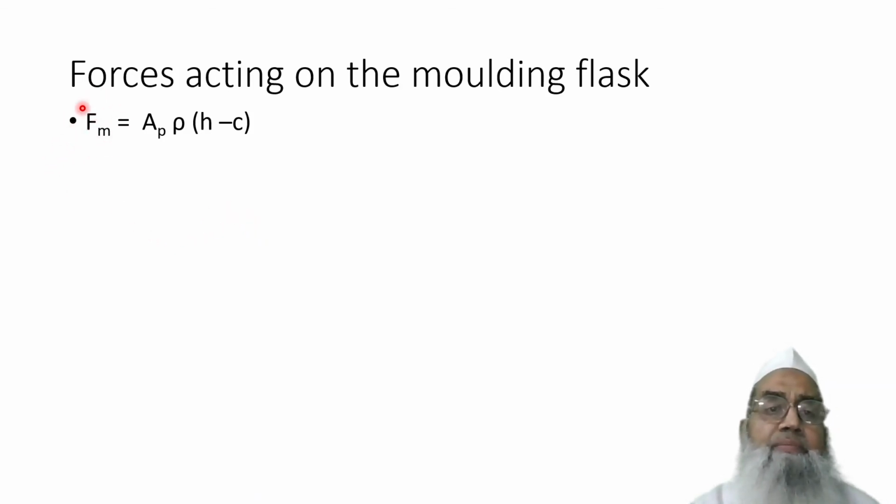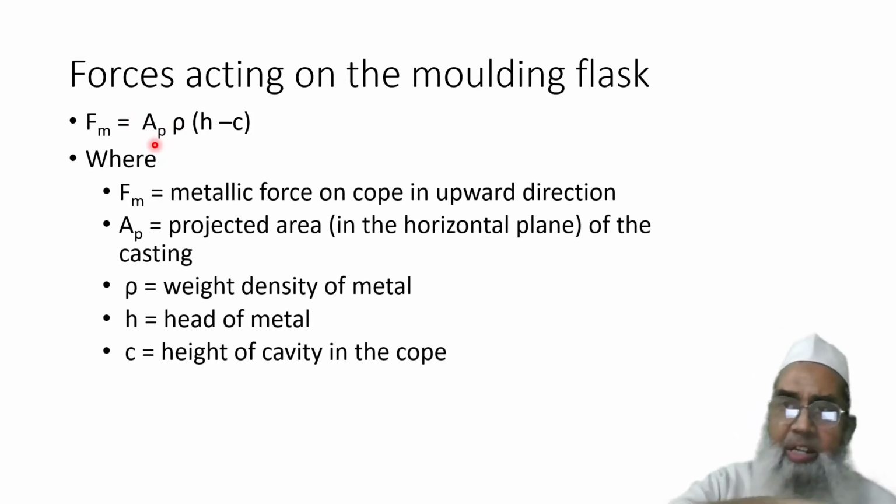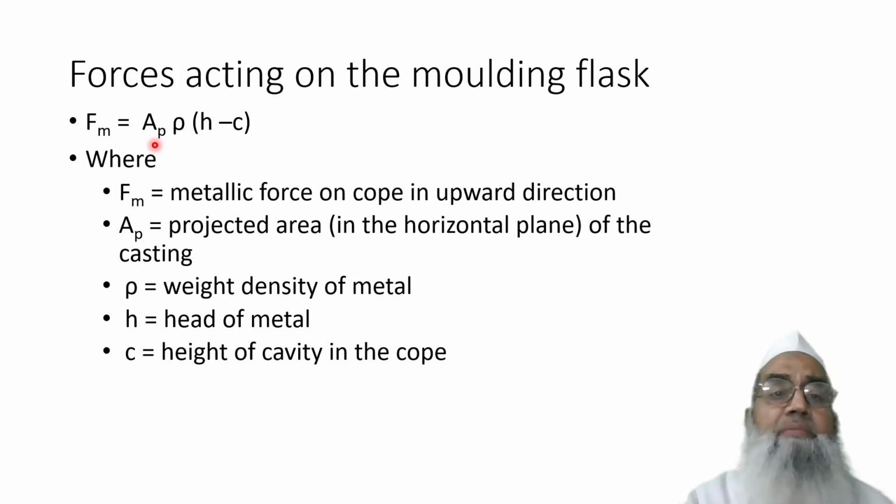This is the buoyancy force, that depends upon the area of the cavity and the weight density of the metal, and this is the head of the metal, the height of the cavity in the cope, and that gives the total buoyancy force acting on the cope.